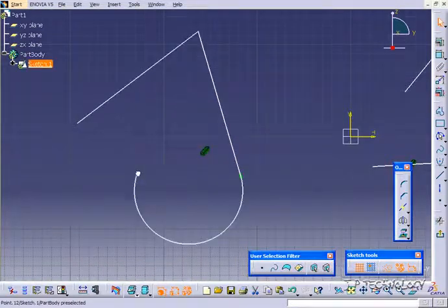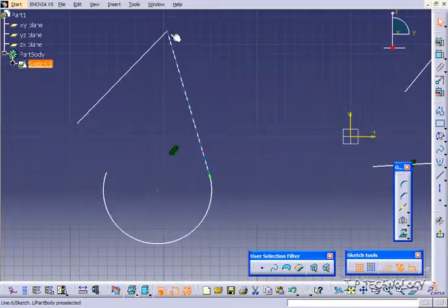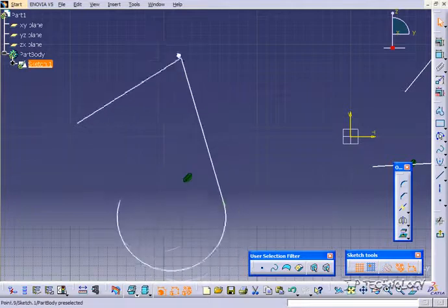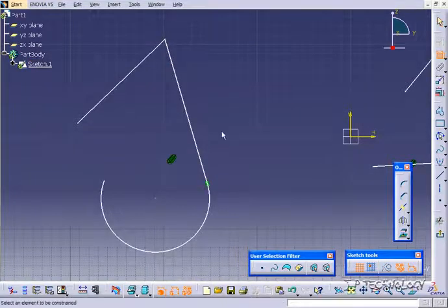And now again, we're not able to change any of the dimensions on these two lines. And if we go to put a dimension on it, you're going to see again that it's purple. So you're able to do one line or multiple lines and fully constrain it.